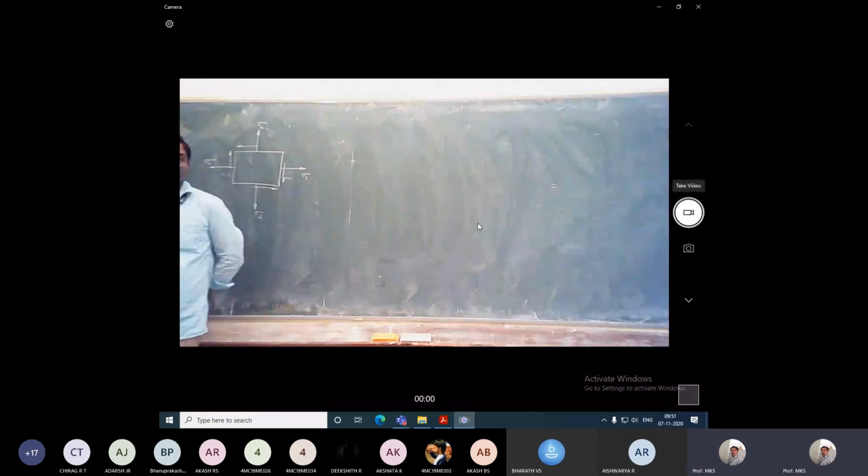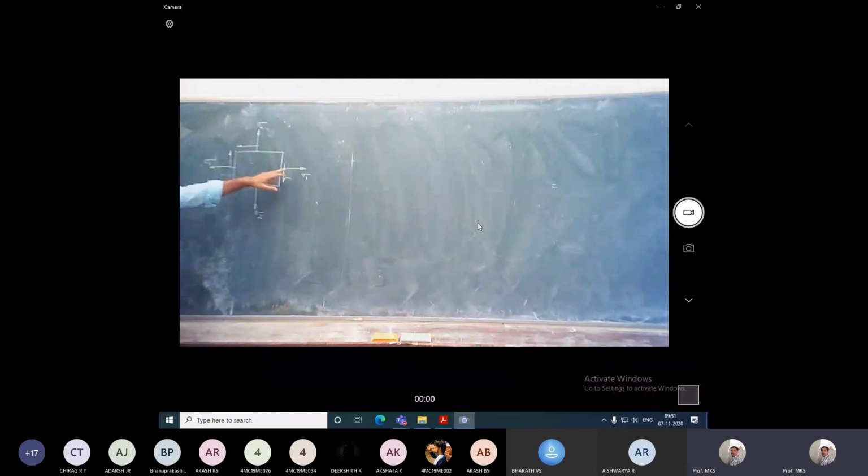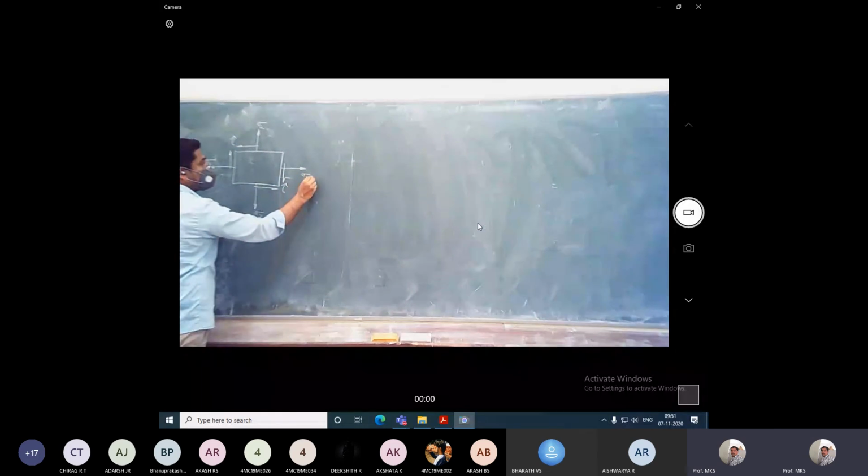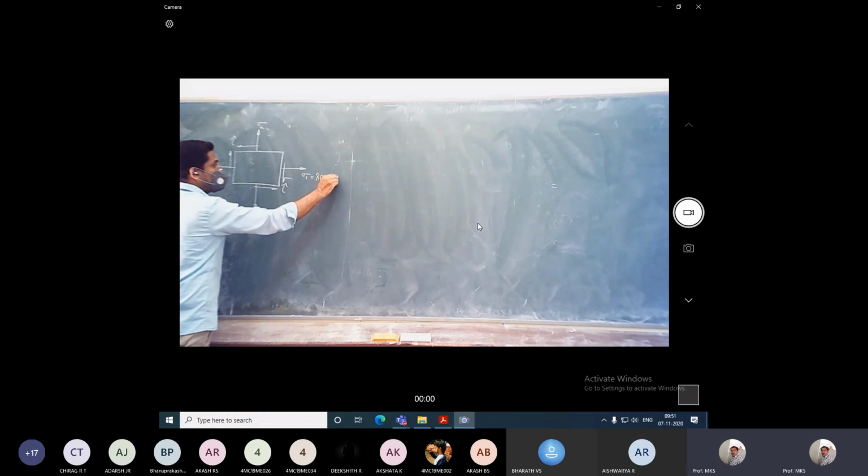Here they have given a plane which is subjected to major stress sigma 1, that is, two perpendicular stresses. Sigma 1 is the major stress, sigma 2 is the minor stress, and these two stresses are accompanied with shear stress tau. The major stress is highest, so this will be equal to 80 Newton per mm square.